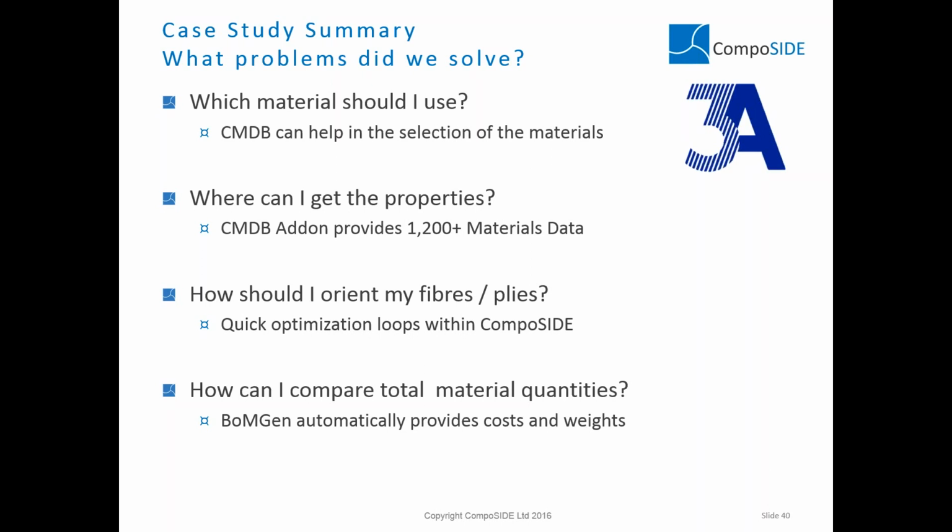One note on the bill of material generator: this can be accessible in a PDF format and HTML format, summarizing the layups used across the part or the structures that was done, and manual elements such as bondings, because here we saw the segment of a sphere. If you imagine, let's say, a dome, based on these spheres, there will be a number of those parts together with joints, whether they are bolted joints or bonded joints. They can be as well documented in your bill of material.